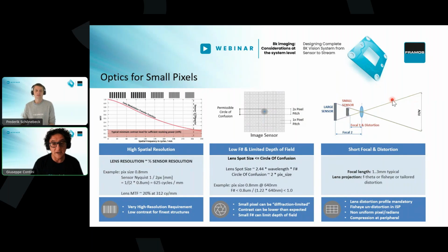So it could be that some sensor has a CRA in the order of 30 degrees. And so this means that you need to have a lens that is matching this CRA. So actually the micro lenses on top of the pixel are shifted in a way to catch wide angle coming from the scene. So the best would be if you have a lens that is matching the sensor CRA, and 30 degrees is quite a lot.